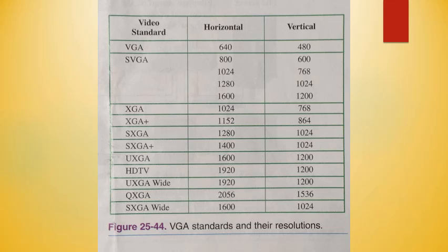A computer CRT uses a shadow mask with openings placed at a much closer interval than those in a television. Also, computer CRT monitors produce sharp images that are rated by dot pitch. Dot pitch is the distance, measured in millimeters, between two dots formed on the display area or screen. The lower the dot pitch number, the crisper the image. The typical dot pitch range is from 0.5 millimeters to 0.30 millimeters.